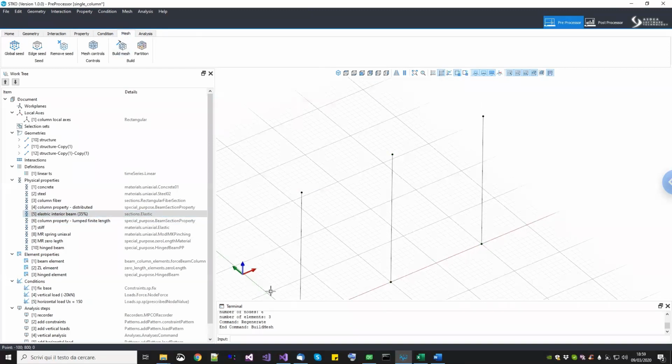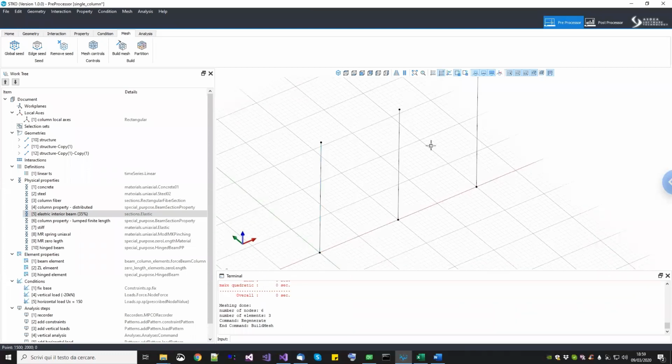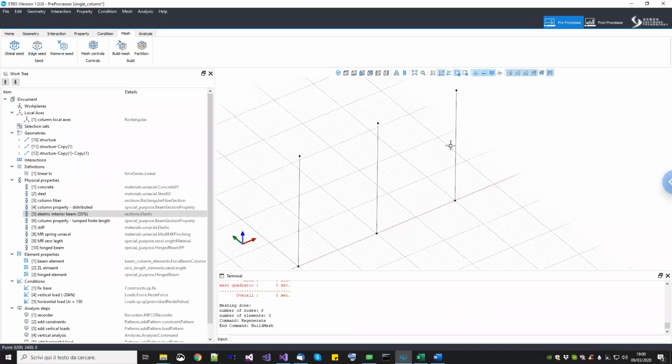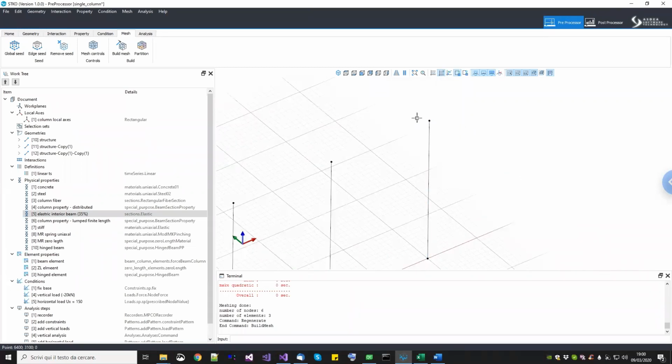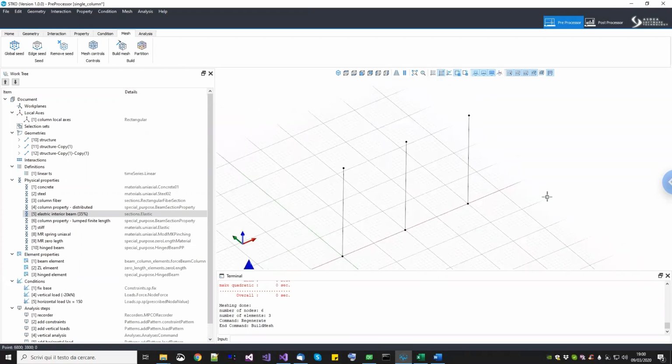As you can see here, in the mesh inside STKO, we just have 3 elements, and of course this is pretty straightforward, and 6 nodes. So at this point, we don't have any spring here. We just have 6 nodes and 3 elements, while we were expecting at least another node here and another node here, and here 3 elements, the element and the 2 zero lengths. Actually, they will be created automatically when STKO writes the TCOD file. So this is very convenient when you have to do a very large structure because you can create a continuous frame structure and then you apply the hinged beam and STKO will separate them for you. Okay. So let's run the analysis.